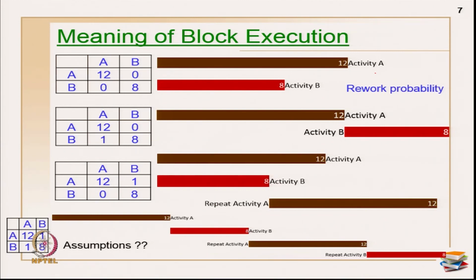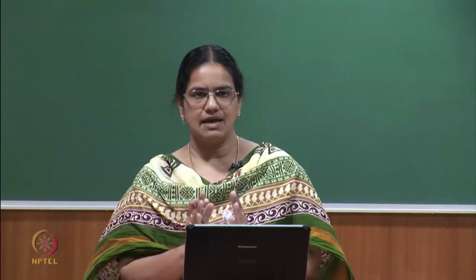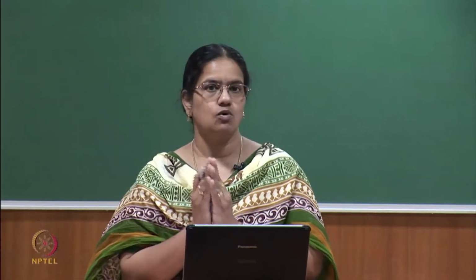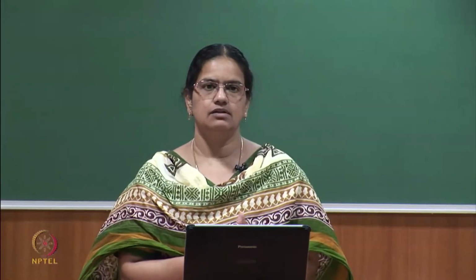This is also a caution you have to keep in mind. The model will not even stop. Whether you are working on a simulation model, it will never even stop. So what should you do? Maximum you can give 0.9 or 0.8 as a value for your rework probability values, and be careful when you are keeping a value as 1, unless you know that 1 will not stop your model. So do not keep a value as 1. For example, in this case that may happen.